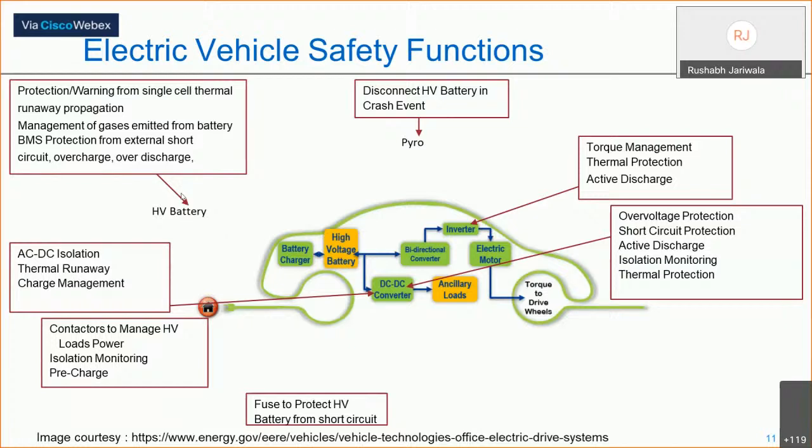But its main responsibility, I would say, is the BMS, battery management system. The battery management system monitors the cells and continuously checks whether all the cells are at the right state of charge, and during charging how much to allow it to charge, and then thermal management and other things.